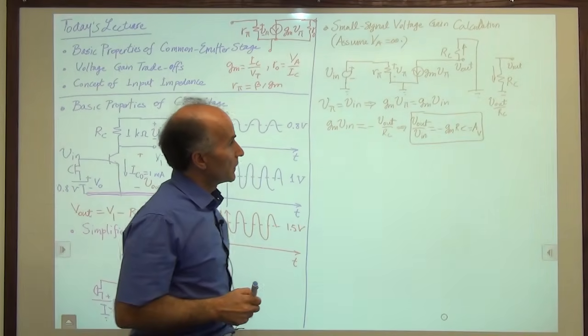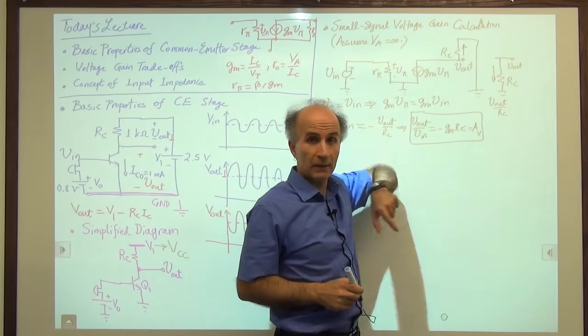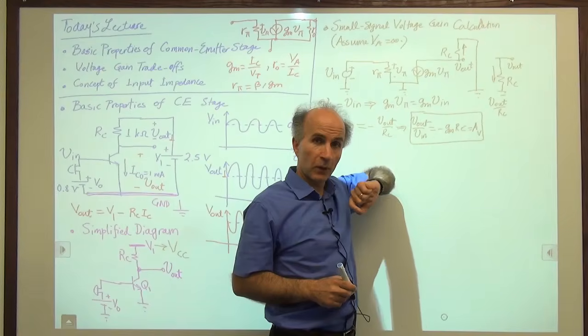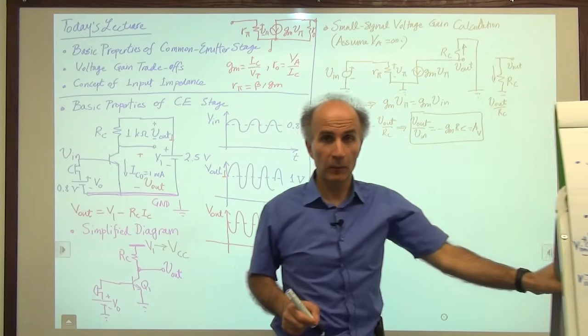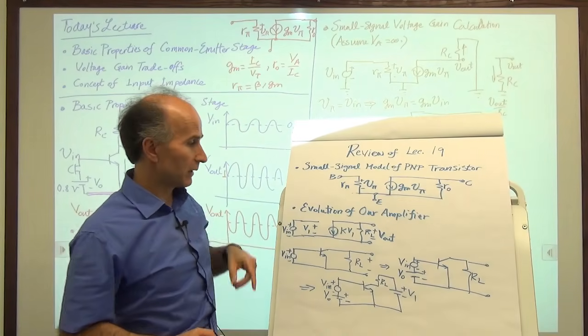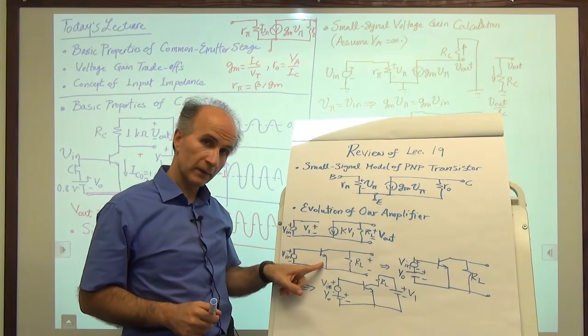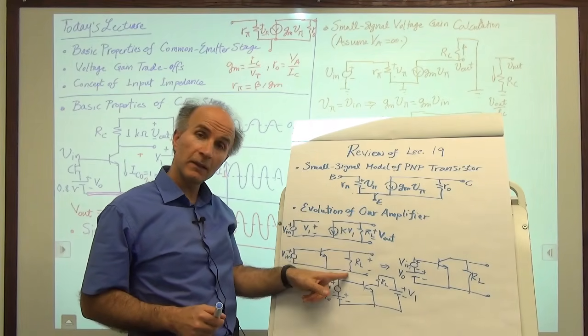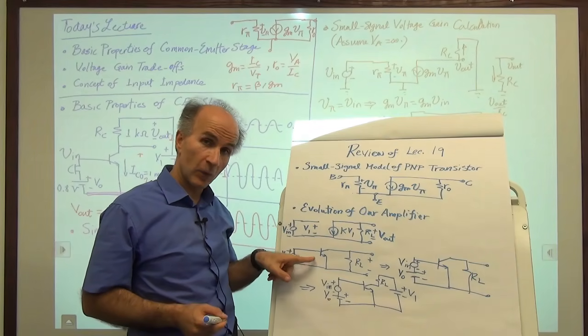Okay, so gm is the transconductance of the device. And now we realize why that very first circuit that we built using the bipolar transistor failed. This circuit here, remember? We connected our microphone directly to it, and we were hoping to have gain. Well, because we had no bias, no collector current, gm was 0.